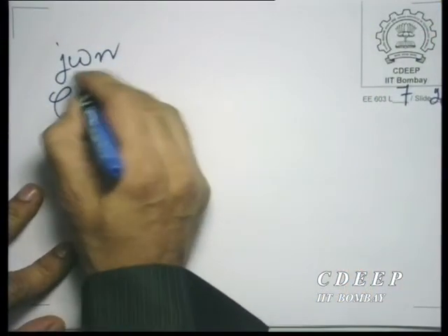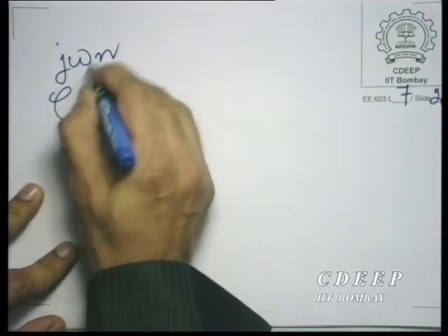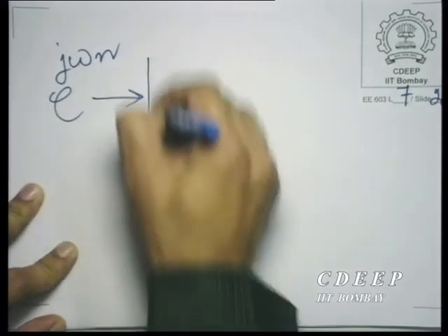All right, then we will agree to use the normalized angular frequency, because we are going to use the integer n to denote the sample number and also to denote the sample time, since the sampling time is unity. So, therefore, we have e raised to the power j omega n as the complex exponential, otherwise we would have to write down e raised to the power omega ts times n and so on. So, we do not need to do that now.